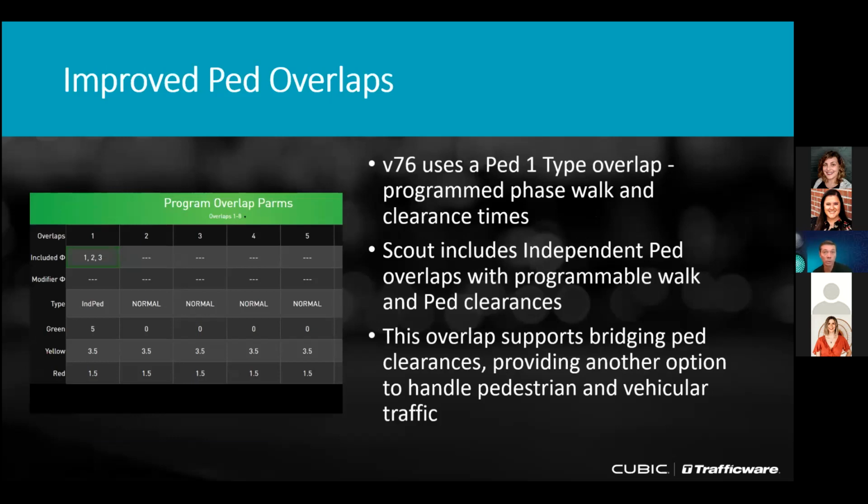With rest and walk, it really seems to make a pretty nice option. It allows non-conflicting phases to begin early, depending on demand. It's beneficial to intersections with big medians or large PED clearances.